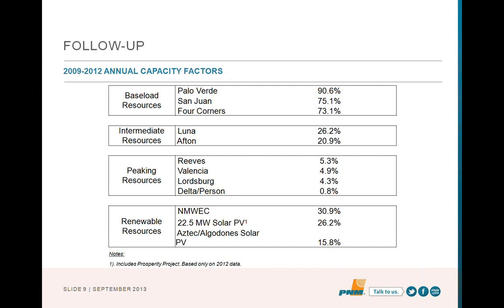It also helps us when the wind stops blowing and our output from a wind farm starts to decrease. We can fill in what we're losing from the wind farm with a gas plant while we're out there trying to make a market purchase or ramp up one of our baseload resources to keep things in balance. So that's the role that the peaking resources play. They're important because you need them there to make sure you're reliable, but you don't run them very much.